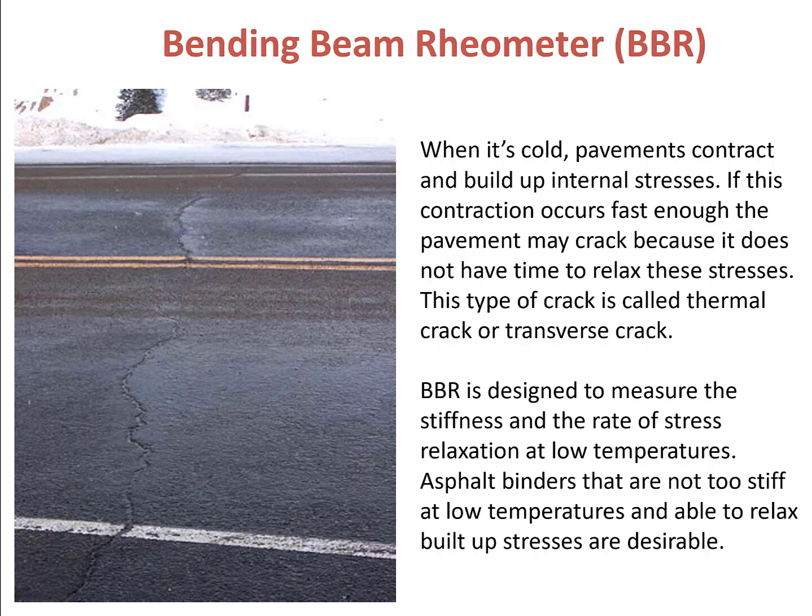This is because the direction of the cracking is always perpendicular to the direction of traffic, as shown in this picture. There are two mechanisms that can cause thermal cracking. The first one is called a single thermal cycle below the critical temperature.